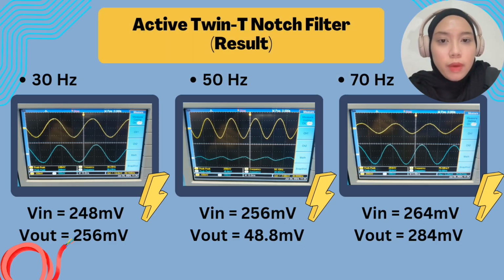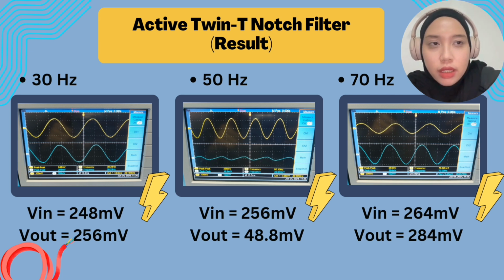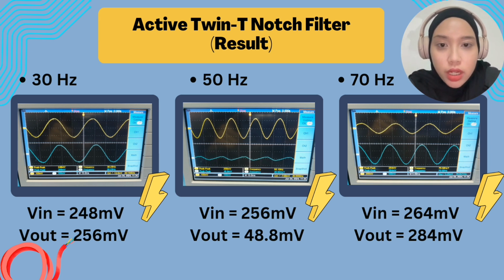Hi, my name is Sorfina Bidomor and my matric number is 22115155, and today I will discuss the results of the active notch filter. This filter serves the crucial purpose of reducing the signal at a specific frequency, which is the desired frequency at 50 Hz, corresponding with the frequency of common power line interference. But for our new project, we use a frequency of 52.63 Hz because of several factors related to the availability of components in the lab.